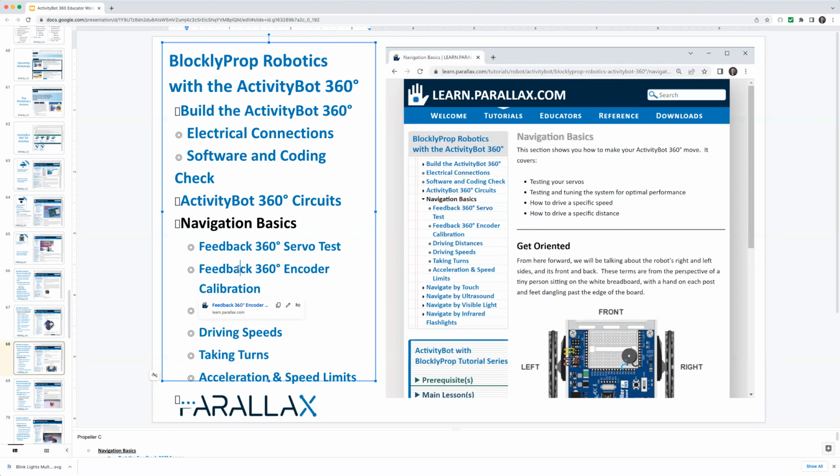Now, this calibration is not required for the thing to function. If you have everything connected properly, it will go from a default calibration. But what the calibration does is it just measures the top speeds of both servos and then records that in some permanent EEPROM memory that is not needed for holding the program. We have a double EEPROM that's twice as large as the 32 kilobyte program space. So it's 64 64K EEPROM, I believe.